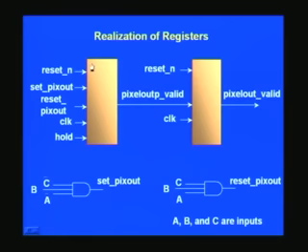Here what you see in the picture is two registers as such. One register output is called pixel out P, P stands for previous, and it is a valid signal. In microprocessors you would have encountered data and its corresponding data valid as such, and this is precisely what it is, and it is a valid signal, not the data itself. Here this is one of the designs I made for video scaling as such. We will not go into the details of the same, and this is just an extract of a portion of that.